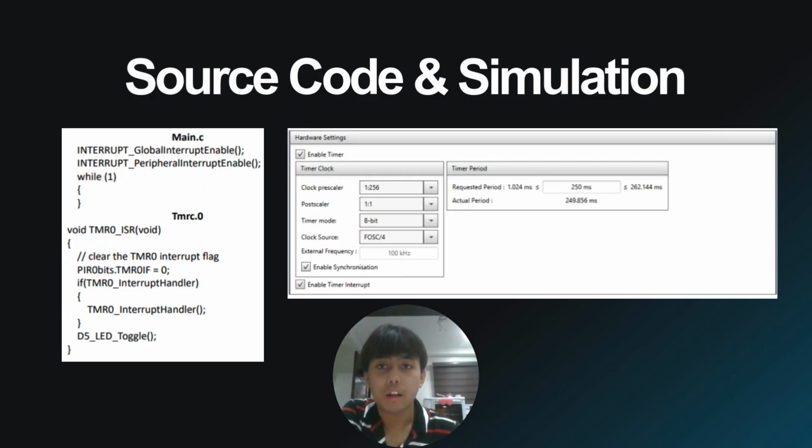For this code used in the C file, it used the interrupt instead of delay polling. The difference between delay polling and interrupt is that interrupt sets up the timer 0 peripheral to generate periodic interrupts. When an interrupt occurs, the microcontroller executes a specific function, which is the ISR, to handle the event. However, delay polling uses a loop to wait for a certain amount of time, during which the microcontroller is often busy doing nothing.